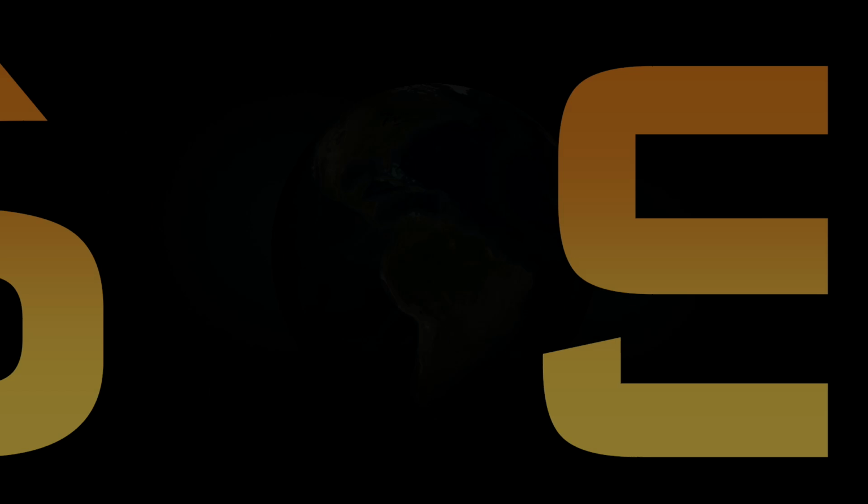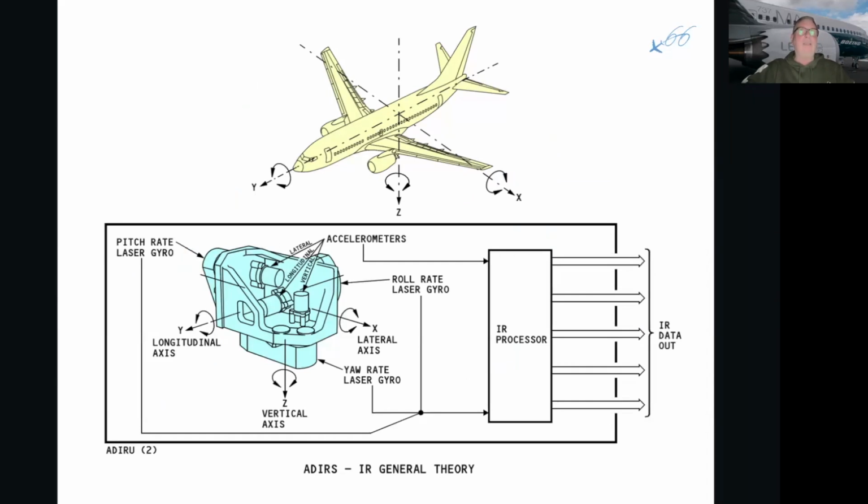What we also need is to know how the IRs work in general. They are 3-axis gyroscopes, so they calculate our position over 3 axes. All right, the X axis is for the pitch. The Y axis is for the roll, and the Z axis is the lateral for the yaw. Those are the 3 axes. So we have 3 laser gyros in 3 planes and 3 accelerometers.